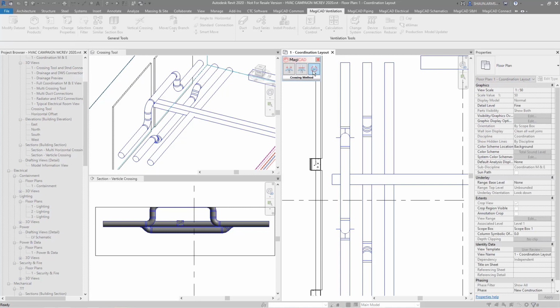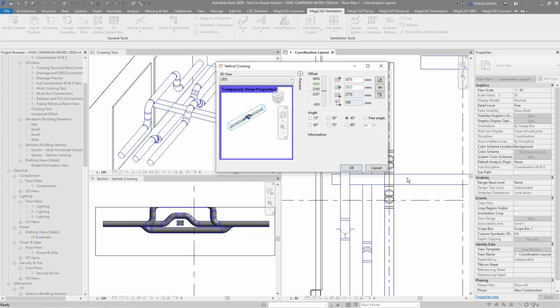And then finally is the Smart tool. So this time, this is going to put the length at the minimum distance available. So I'll select the duct I want to amend, and then the object that I want to avoid. So that's 2 clicks this time. And you'll notice it has done the minimum achievable to get up and over that obstacle. And again, I can change offsets if needs be, and it will let me know if it's possible or not.